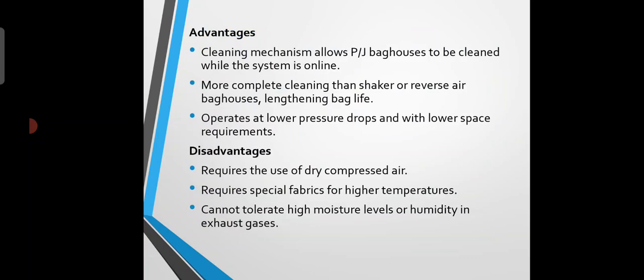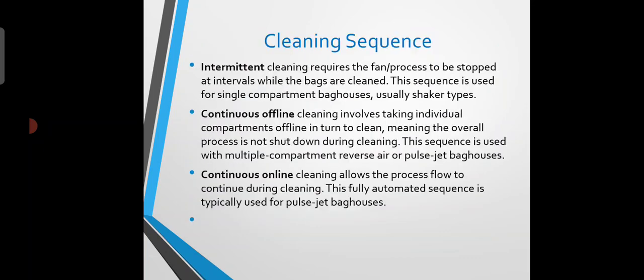It lengthens the life of the bag, operates at low pressure drops and with lower space requirement. Disadvantages are it requires the use of dry compressed air, requires special fabric for higher temperature, and cannot tolerate high moisture level or humidity in the exhaust gases.